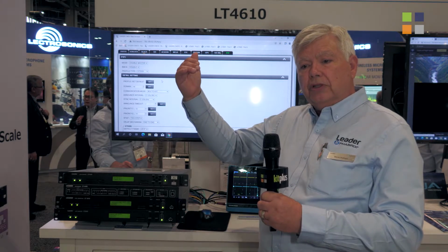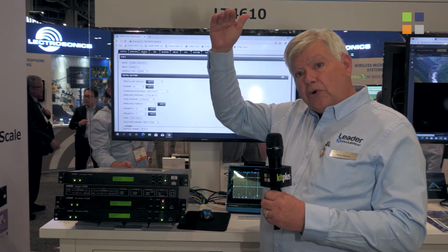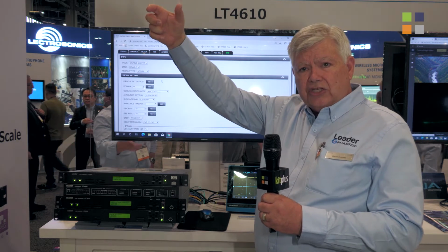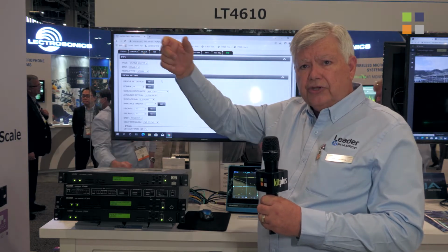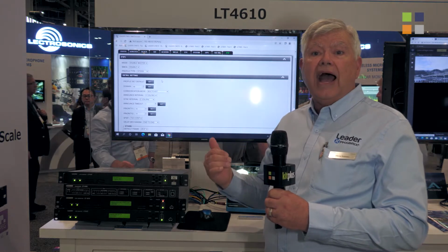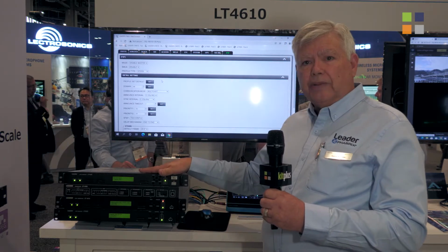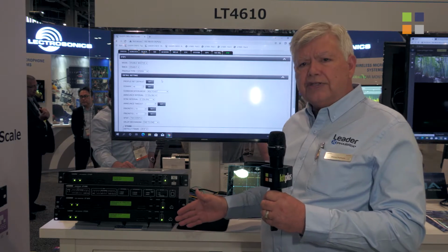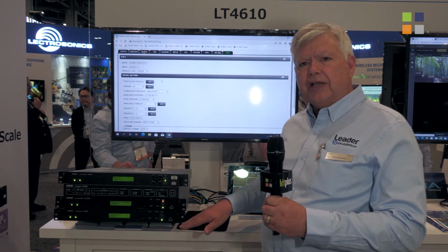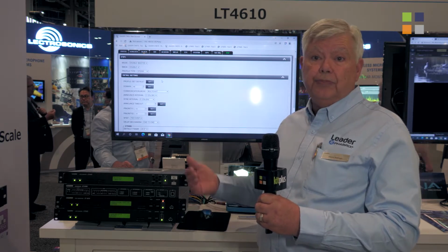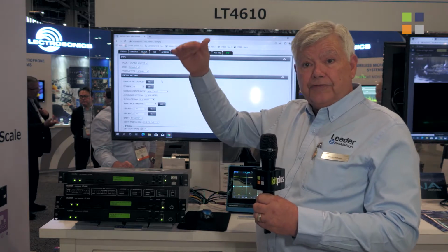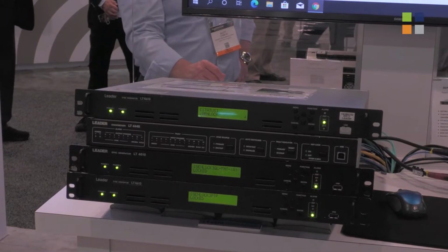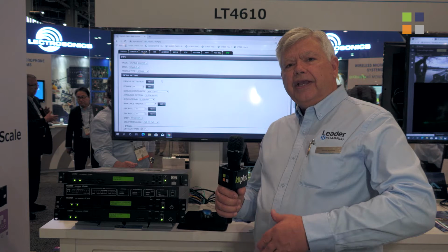that may be in a remote location, multiple floors in a building, so that we can turn around and regenerate now all the sync signals that you need, all the test patterns that you need that are still locked to the house reference. So we can generate PTP, it's perfectly locked to black. We can generate all the test patterns and be able to resync and have the generator lock to PTP at a remote spot within your facility to turn around and recreate all of those test signals that you need and need them locked to house sync. And now we're going to look at the LVB440.